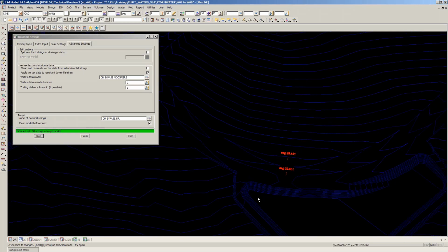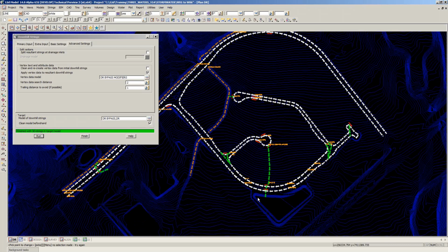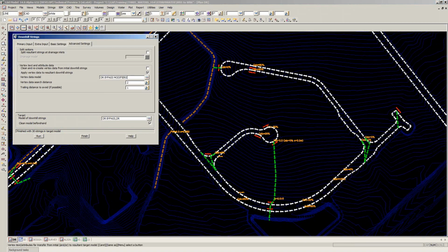The main reason it's there is because your road design might have changed significantly. The roads might be wider, there might be a road disappearing, and we don't necessarily want this information to disappear if it doesn't get reapplied somewhere. You'll be able to do a cross-check against this model and your new model to see, did everything get applied that I expected it to? If not, you might need to change some things and all of that. We just don't want that information to disappear.